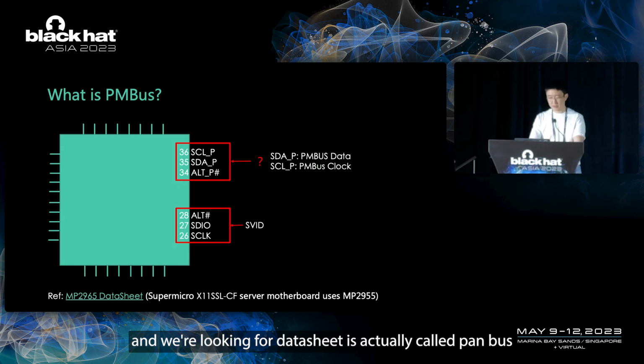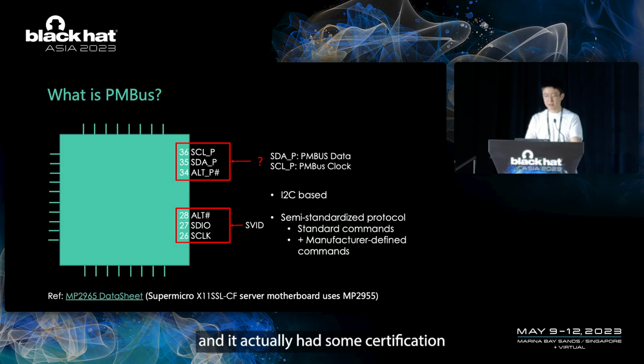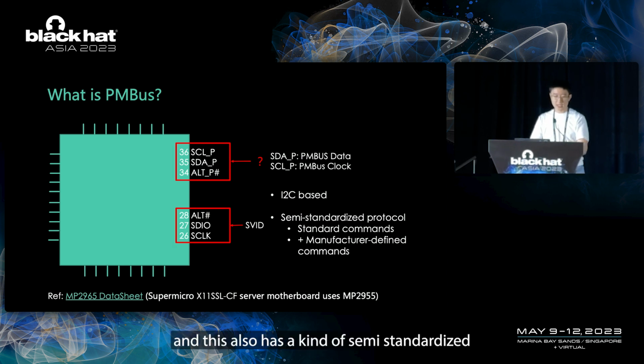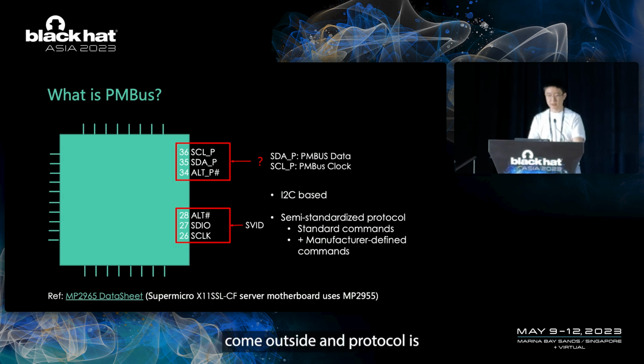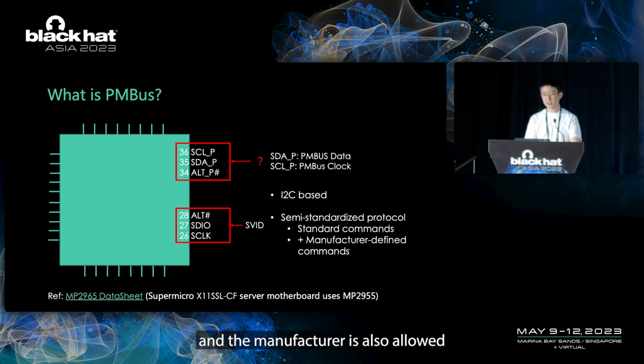It's actually called PMBus, which stands for Power Management Bus. It has a specification. It's an I2C-based protocol, and it also has a semi-standardized command set and protocol. That means the PMBus specification specifies some standard commands, and the manufacturer is also allowed to define their own commands.